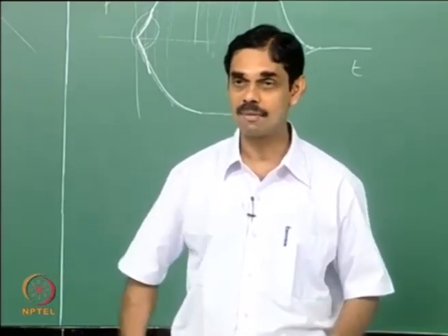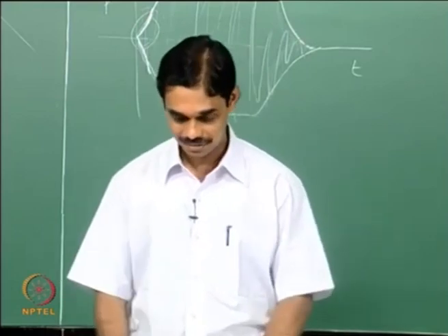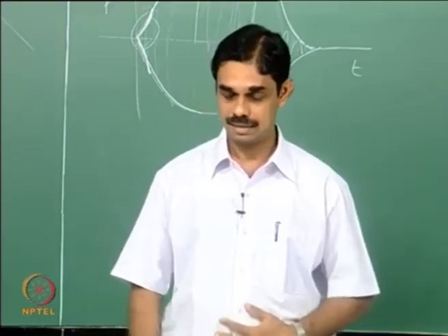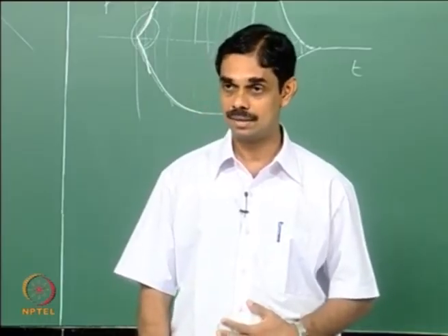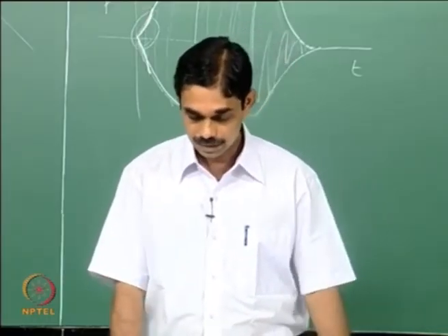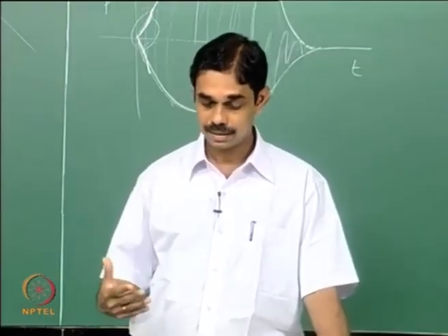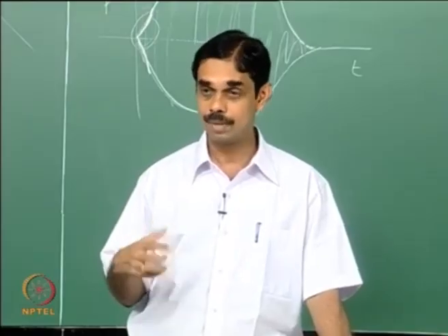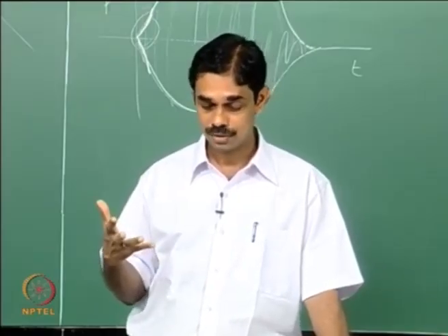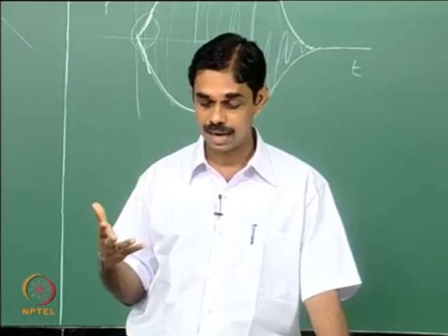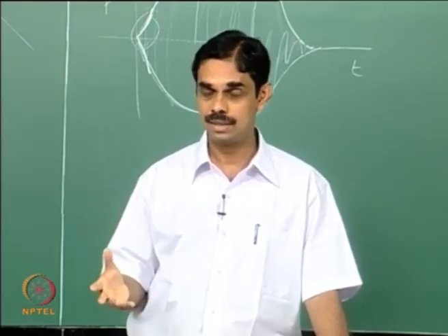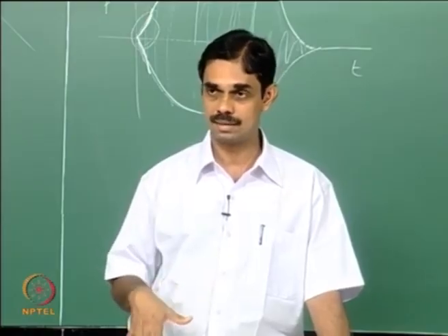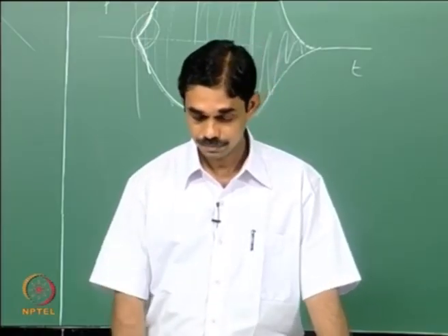Now the last thing I want to speak about before I close off this course is particle effects. So you have particles that are added, primarily for damping the oscillations, and the most common particle is aluminum. So aluminum burns to form alumina. There are also things like zirconium carbide which are added as stability additives. They not only form this particle, but they also influence the reactions at the surface and so on.